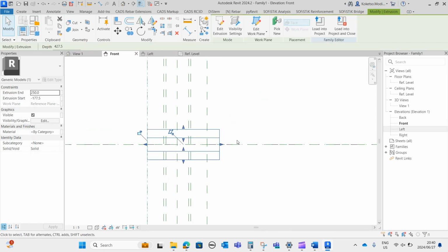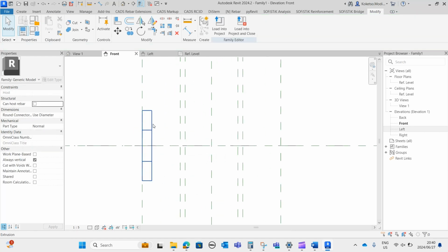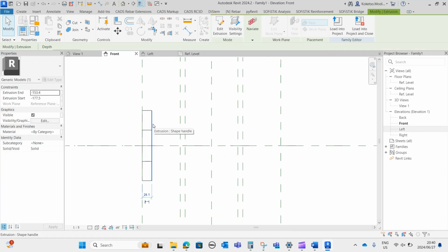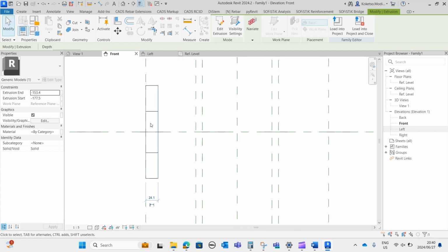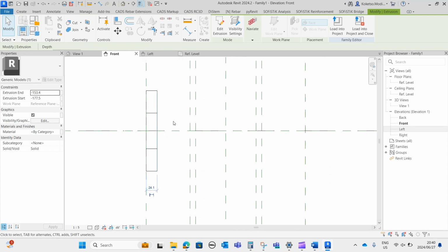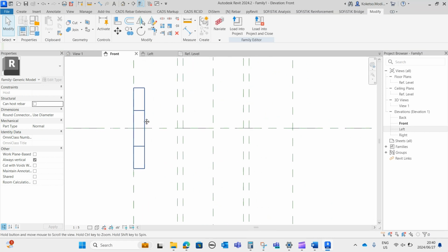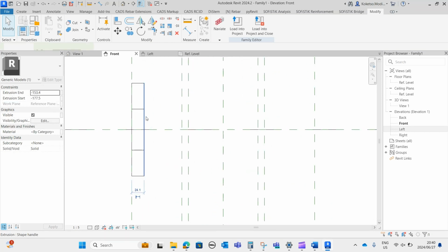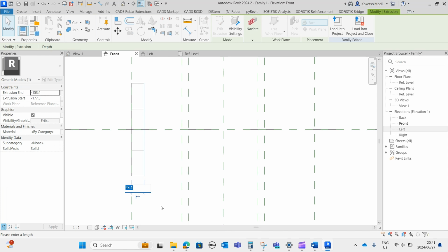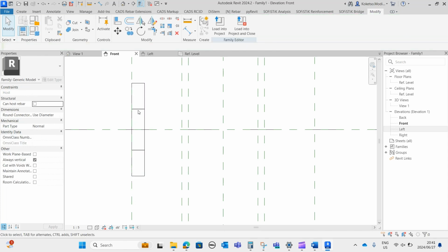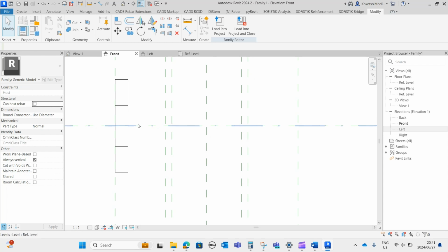So I'm gonna drag it towards the right. And then, so the thickness of this part, okay, I'm gonna call this one the left insertion point of our T pipe valve. And so the thickness, I'm going to make it 25 millimeters, and then I'm just going to place it like that.